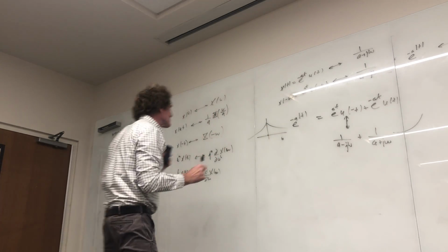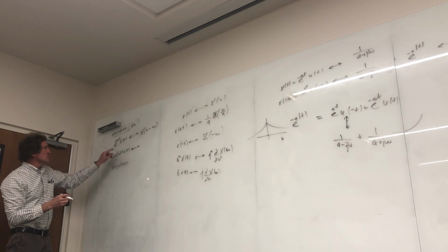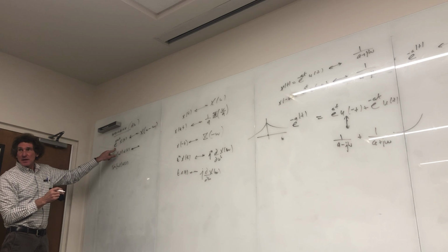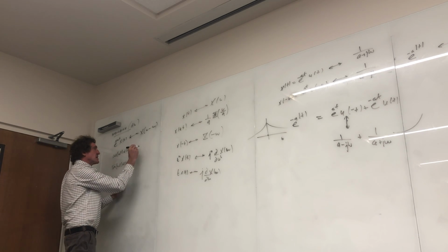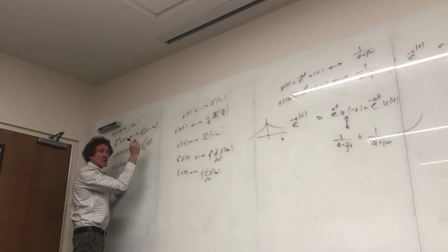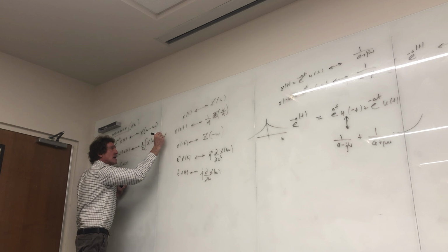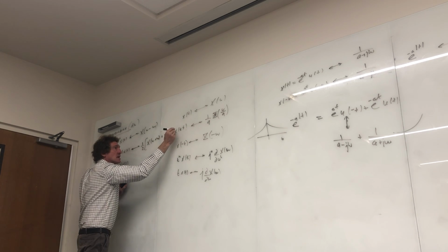Now for this one, actually, let's do the cosine one for that. What happens to the cosine? Remember how I broke the cosine down into two exponentials and then did it? That just takes it and makes it 1/2. Your book doesn't have this, by the way. I write this down: X of omega plus omega naught plus X of omega minus omega naught.